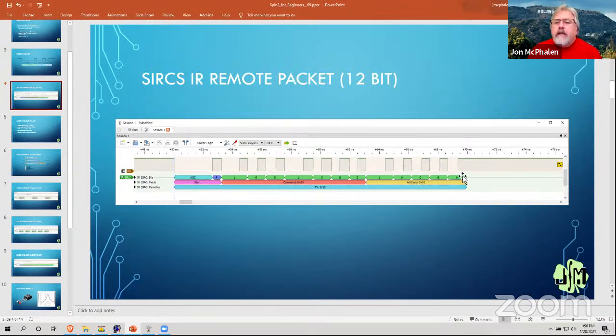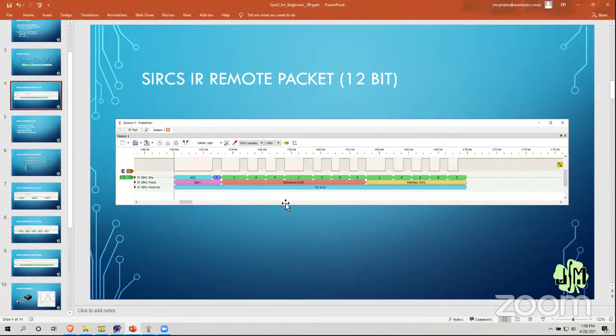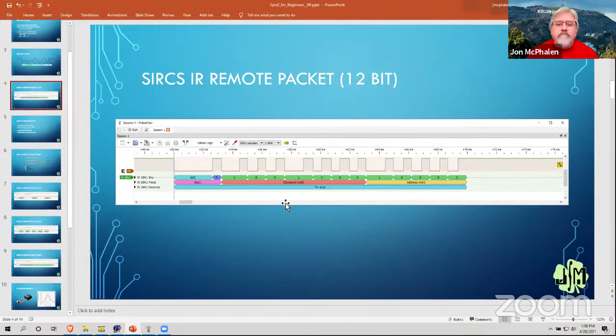And so the 1 in this 5-bit field is going to be the address 1, which is again a TV remote. And then the buttons on the keypad in the 12-bit code, the number pads are the code for them, or the command for them is the number that's on the key minus 1. So when we press the 1 button, we get the 0 in the command field. What do you get when you press 0? You get 9. So it acts like 10.